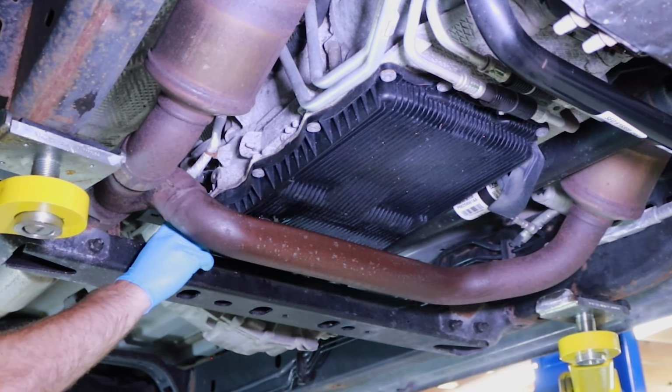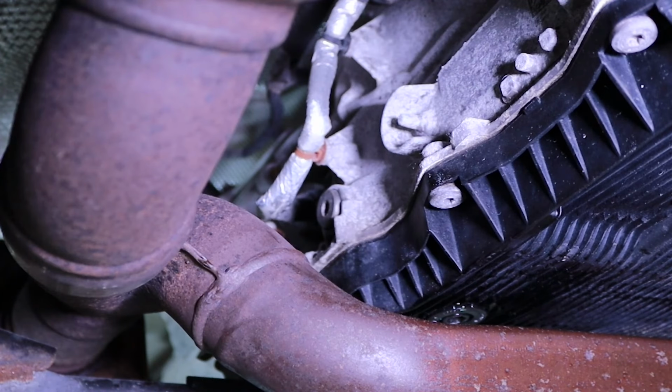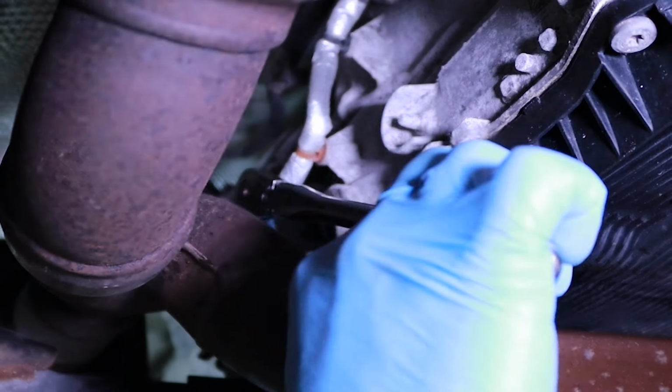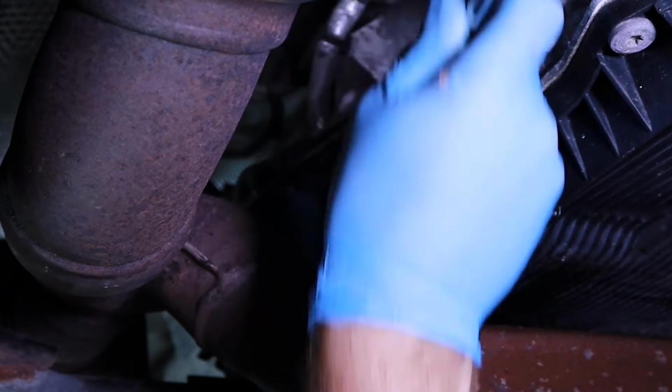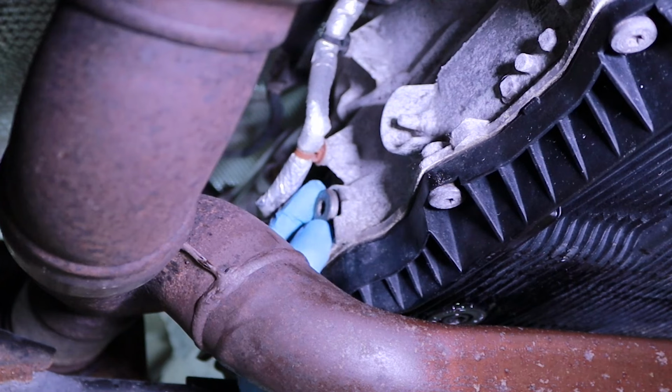Next, locate and loosen the transmission fluid fill plug. This is found on the passenger side right rear area of the transmission, just above the exhaust. Before draining the transmission fluid, loosen and remove the fill plug in a counterclockwise direction using an 8mm hex bit socket and ratchet. This will confirm that you will have a way to refill the transmission with fluid in case the fill plug is seized or can't be removed.